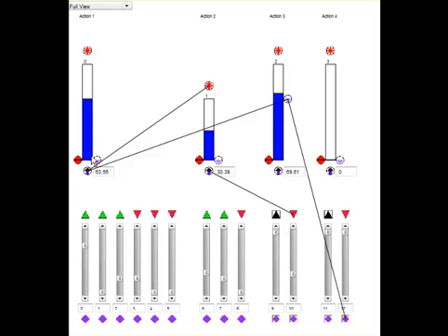Now we will discuss the wires that you see. These wires create functional relationships between the data items. Right at the bottom of Action 1, you'll see a box with the amount, percentage, that is currently in Action 1. Just to the left, you'll see a blue arrow with a circle around it. This is a connection point that we call the modify value. When you left-click on it, two of the wires will turn red.